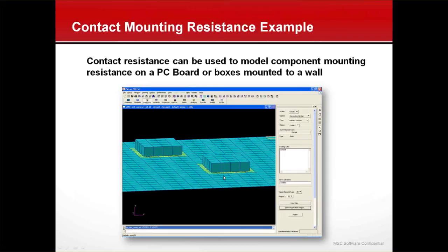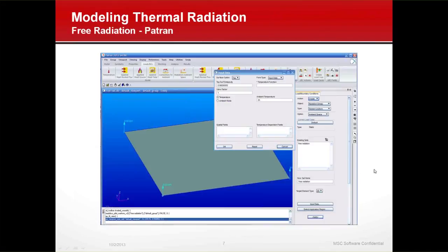You can do it at an element face level or element edge level, but typically we do it at the geometry level. You can do this even without a mesh, or turn off the mesh and just deal with the geometry, and then whatever mesh you use, it will then hook up the right elements. So that's done fairly easily, and I'll show you that in a few minutes.